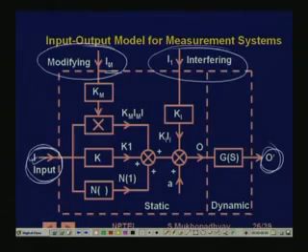It also causes a resistance change which is thermally induced by the thermal coefficient of the resistance, so that is an additive error, in which case the same ambient temperature is actually acting as an interfering input. So in other words, there are several modifying and interfering inputs, and we capture the output finally as, you know, so this is the main path.